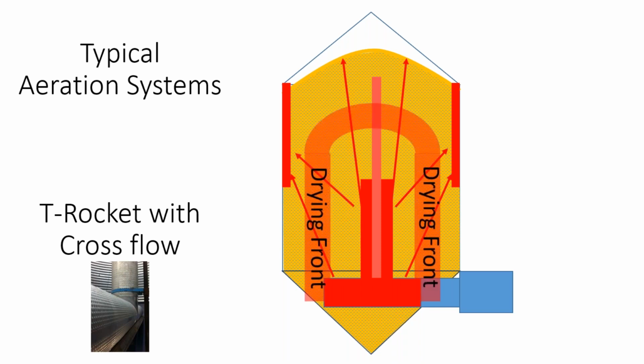With this system, the drying front would slowly move radially outward from the core. And again, I like injecting into the core. It just gives you the confidence that you are getting enough airflow, and the fact that the core is a little bit more dense with the chaff means that you will get good airflow.